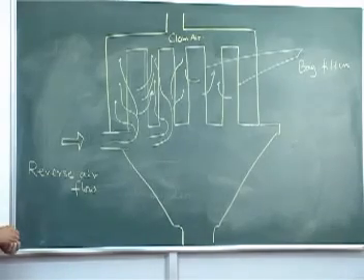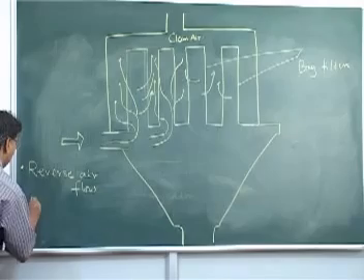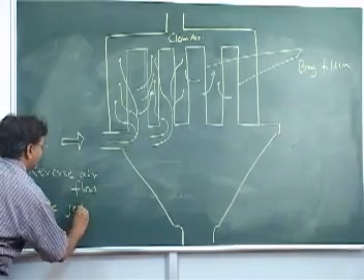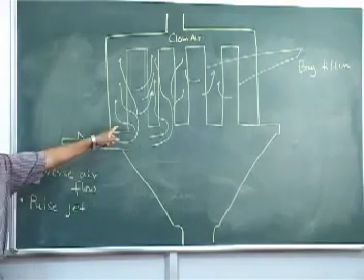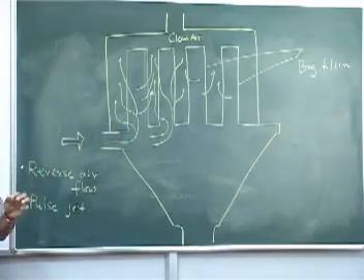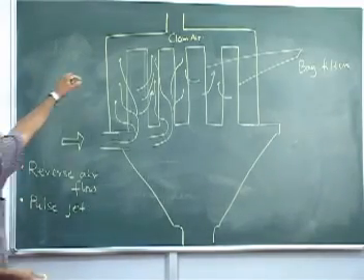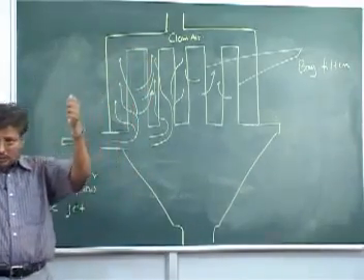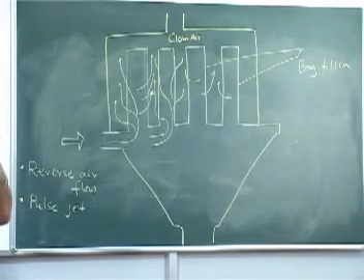The second thing, which is also very common, is pulse jet. The fabric filter, as you see here, is put onto a little steel cage. Otherwise, how will it stand? You can hang it up like this, or you put a steel cage, put that thing onto there, as if you are putting a cloth onto the cage.